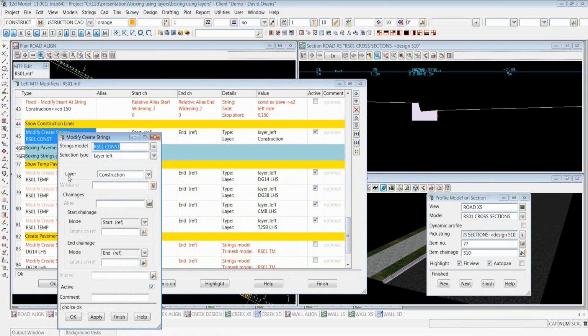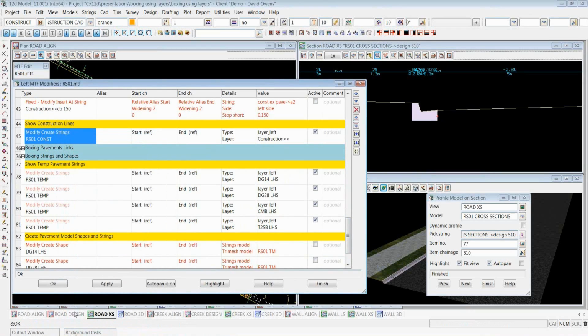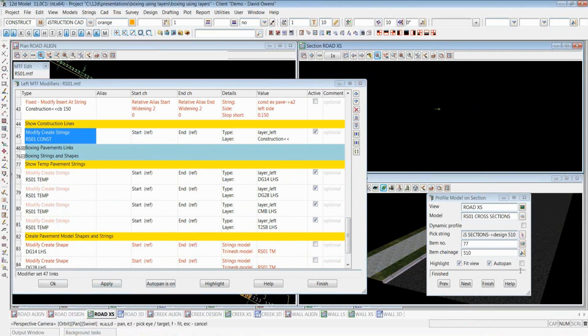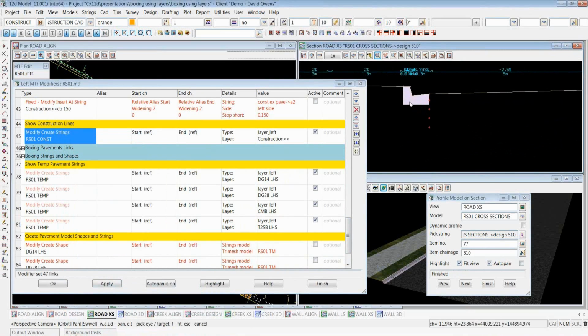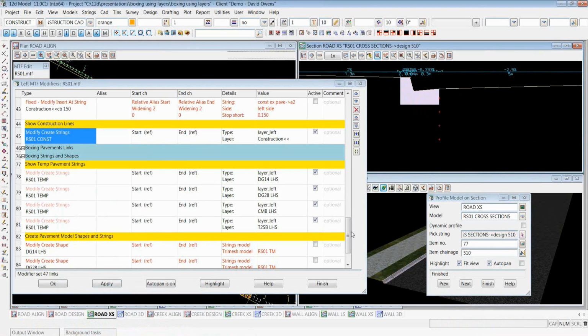On my construction model, I'm going to put all the links that I've added to my construction layer so I can just see them get created. And then I can use my middle mouse button to simply pick them when I need them later on in other commands. So when I run this apply now, I've created a little vertical part of my grid with points at my different pavement depths, thicknesses.